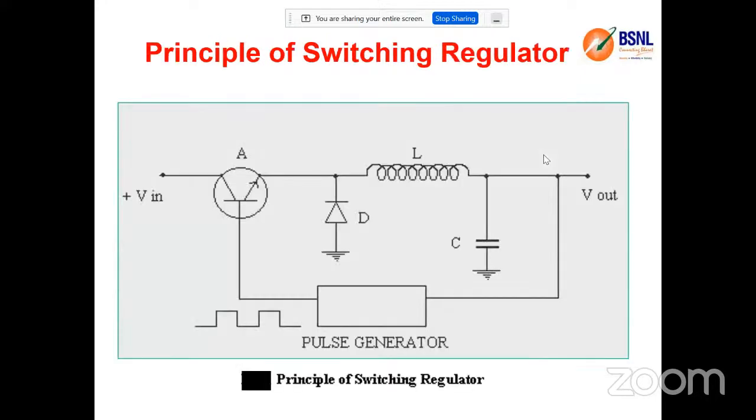Thank you. This is again a part of the SMPS power plant. This is explaining how the duty cycles are adjusted and how the transistor acts as a switch. Here it is a base current. With the help of these pulses, this transistor can act as a switch so that the input can be passed on to the output. SMPS means switch mode power supply. Here the transistor is acting as a switch to convert AC into DC as well as DC into AC, so that we can have a high frequency AC.